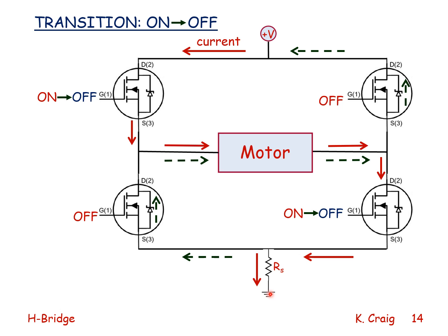When the transistors are turned off, the energy that's present in the magnetic field of the motor windings dissipates by allowing the current to flow as shown by the dashed blue lines. And the current flows in the direction of the Schottky diodes. So the current flows as shown here through the Schottky diode of the lower left transistor, back through the motor, through the Schottky diode of the upper right transistor, and back to the power supply. This is how we prevent any voltage spikes from occurring and damaging the transistors.